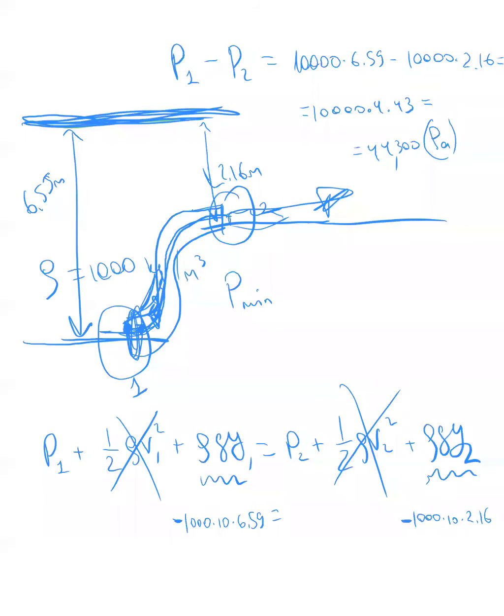So the sign here kind of makes sense. And it makes sense because I need to have more pressure here compared to there at point 1, so that this pressure difference drives sewage water up and against gravity.